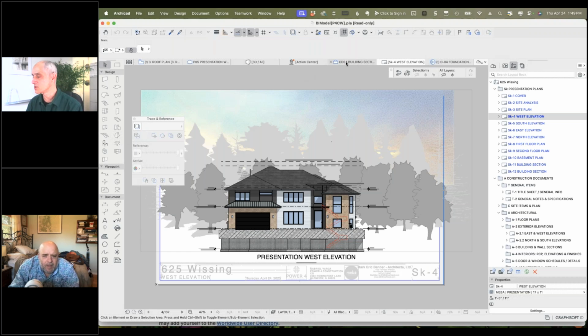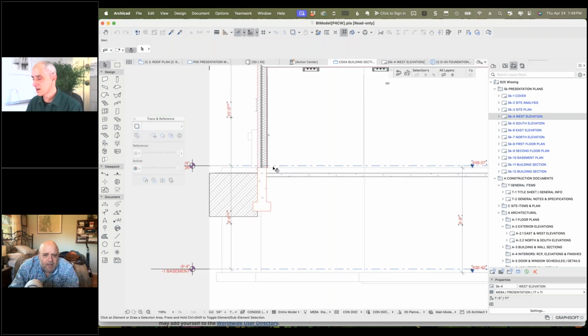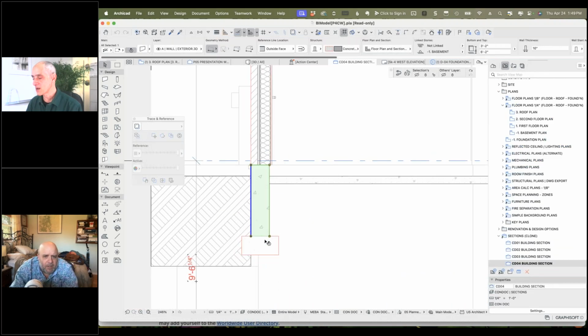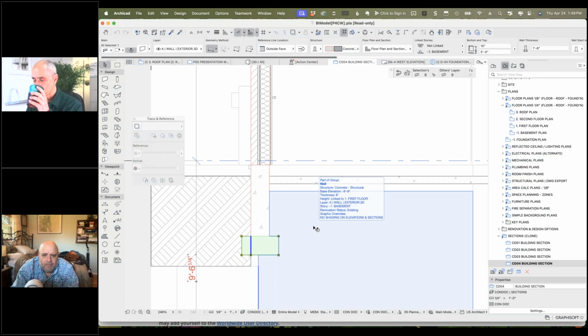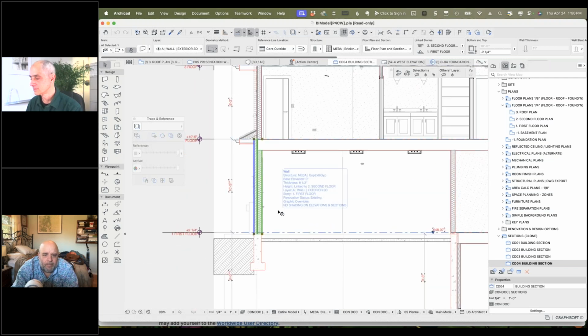Do you want to take a section, let's say, you have in the tab? So we've got, you're doing the stem wall and the footing as separate elements. Do you always do that, or do you use complex profiles for some of them? I have occasionally done complex profiles, but I just feel more comfortable with breaking it into two elements and a little more control over how the foundation and the footing are illustrated.